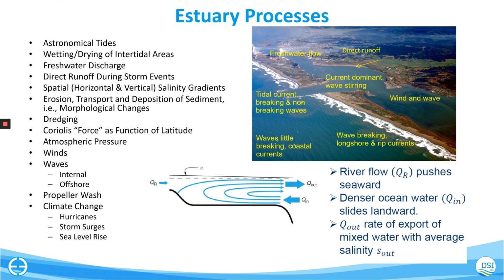Depending on how large your estuary is, the Coriolis force might be a factor, and that will induce a rotation in the water body that you'll see in the velocity patterns. Again, depending on how large the area of interest you have is, the differential pressure throughout the model domain might be a factor as well that you want to consider.